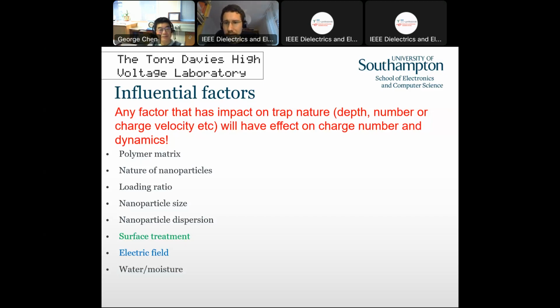Then we have another experimental question. Is there any other method to carry out the space charge distribution experiment without using PEA and ISPD? Yes, there are plenty of other techniques used as well, such as the thermal step method or thermal pulse method, and also the LIPP method, laser-induced pressure pulse, or the pressure wave propagation method. There are a few. They were all developed around the same time, in the 1980s, as I mentioned earlier. So yes, you can use other methods to monitor the space charge in dielectrics in general.